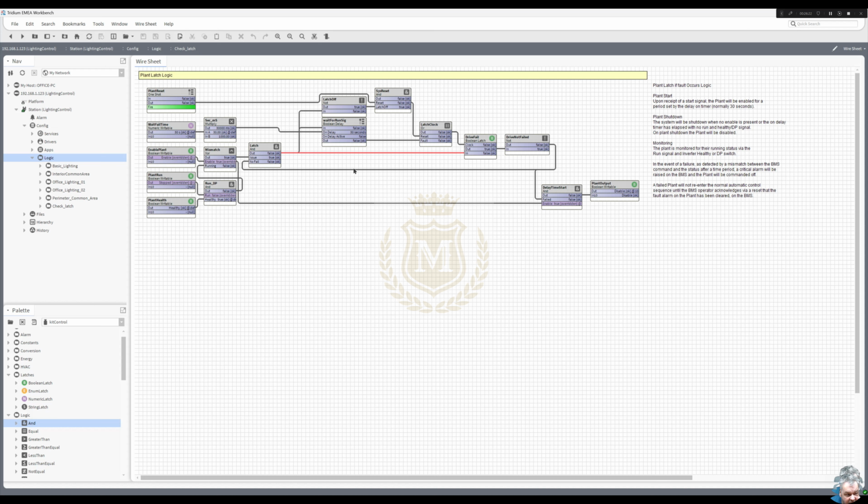And then that's coming back and now changing that to a false. But we've got a failed coming down there. So even though we've got a true, we've got a fail, so we won't run that. So the only time we can actually run that now is when we do a reset. So when we hit that reset, we make that a true in that AND gate, which gives us a true there. So have I got that in the wrong? I have, haven't I? Makes that a true there. True in the OR gate. Puts that to true, which puts that back to false.